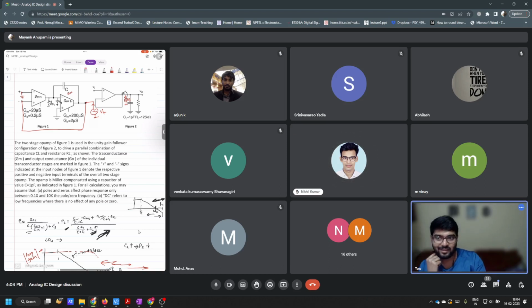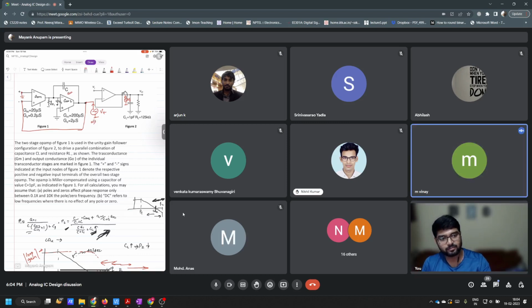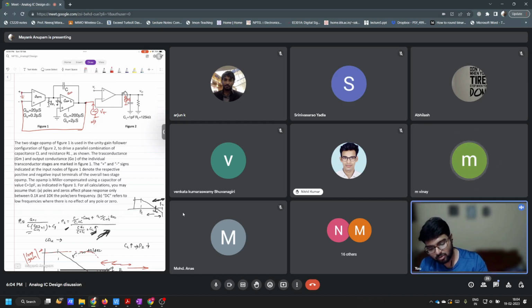No, no, no, nothing will be like that. It will be like this. You solve it by writing the KCL and KVL equations, and you will find it. Sir, in that case, which frequency should I take to calculate ROUT? You do not have to assume any frequency. You have to do everything in terms of S.